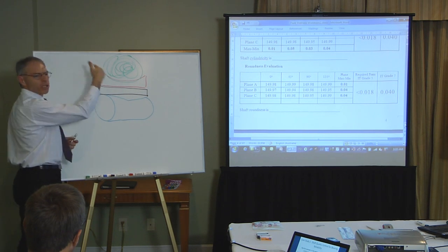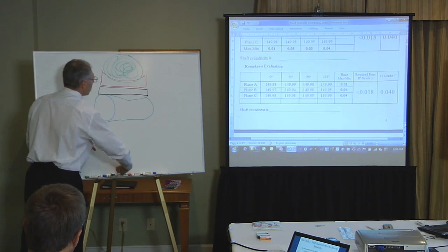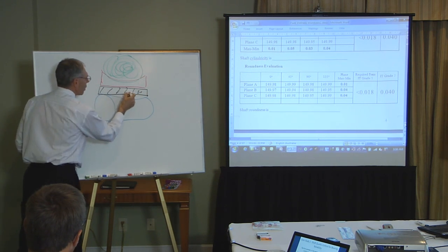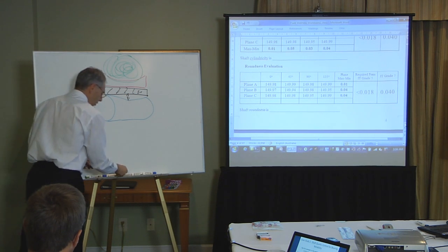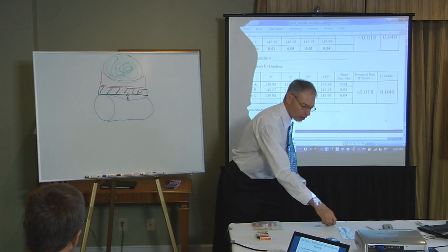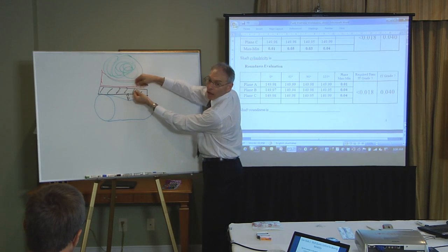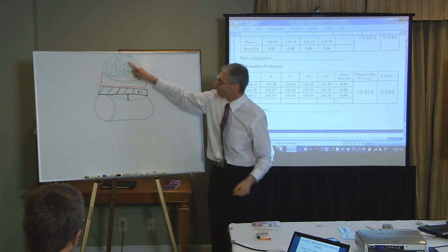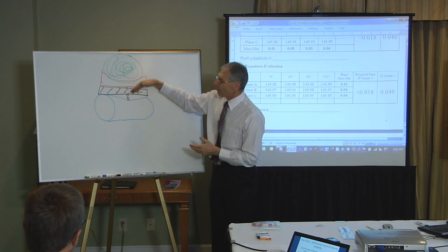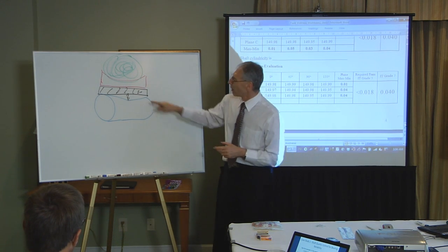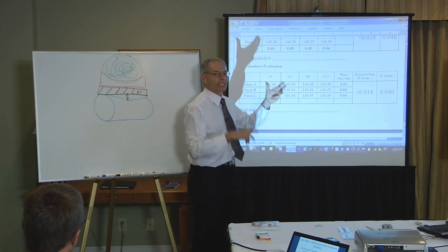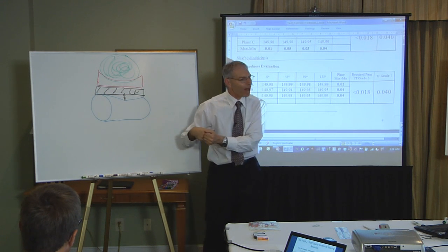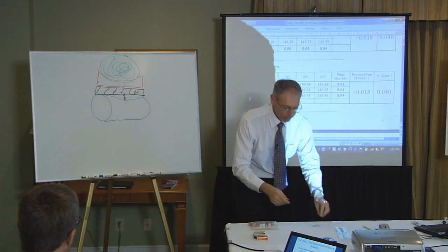So every time the rolling element goes over this gap here, this sleeve flexes down, flexes back. 3,000 times a minute if it's a two-pole motor, depending upon how many elements there are as well. So that's why the bearing was failing within a couple of weeks. This gap, because the shaft is unsuitable for the job, was allowing the whole bearing to flex. Eventually that would fatigue very, very fast, and of course it breaks.